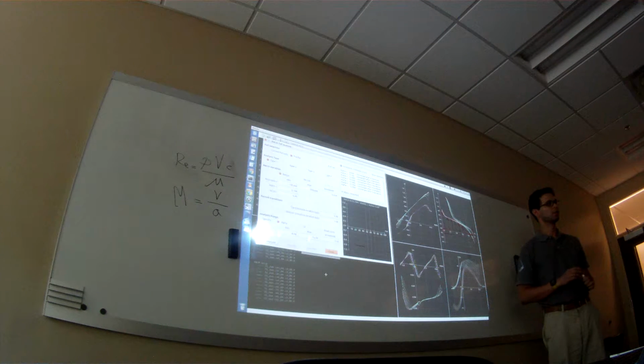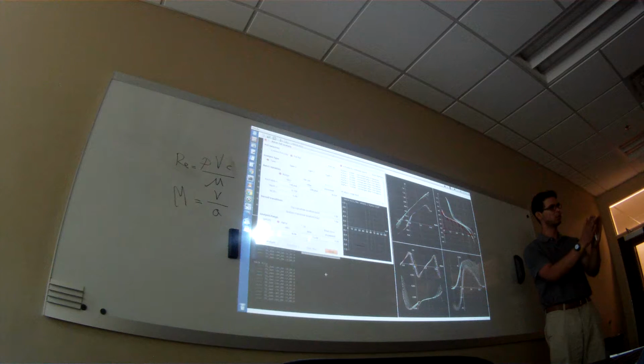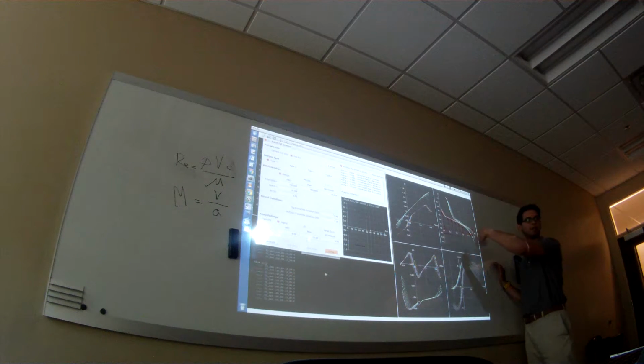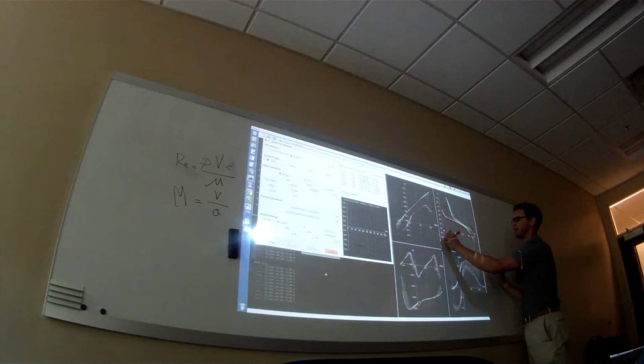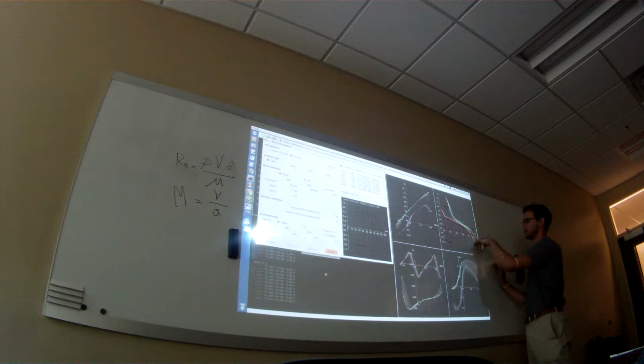You find the center and the total force, right? So you integrate across the entire thing, find the area under the curve, and you get the total lift. And you'll also find out where that acts, right? If I have lift at a certain point, what's that going to do here? It's going to cause a moment.